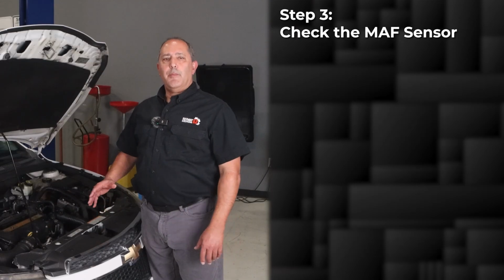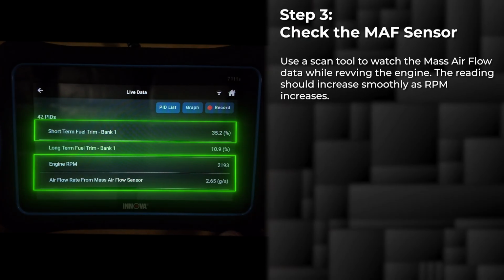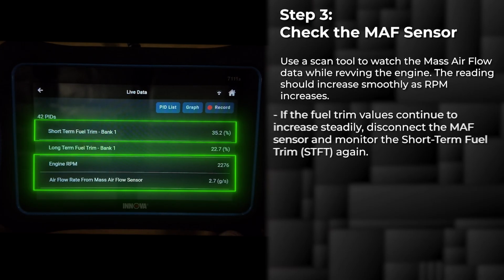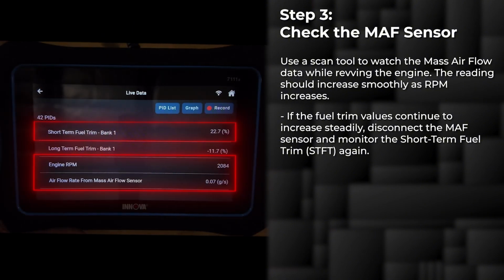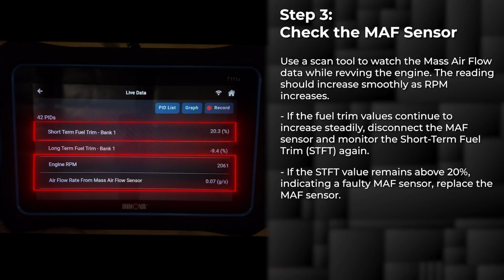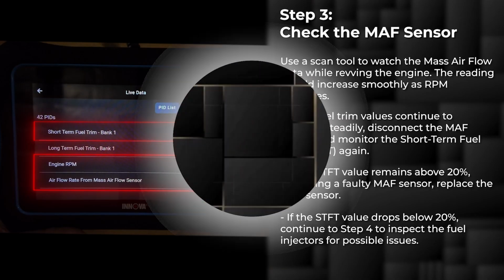Step 3, check the mass airflow sensor. Using the scan tool, watch the MAF values while revving the engine. The reading should increase smoothly as the RPMs increase. If the fuel trim values are still out of range, disconnect the mass airflow sensor and check the short-term fuel trim again. If the data value is above 20%, replace the mass airflow sensor. If the data value is below 20%, continue to step 4.